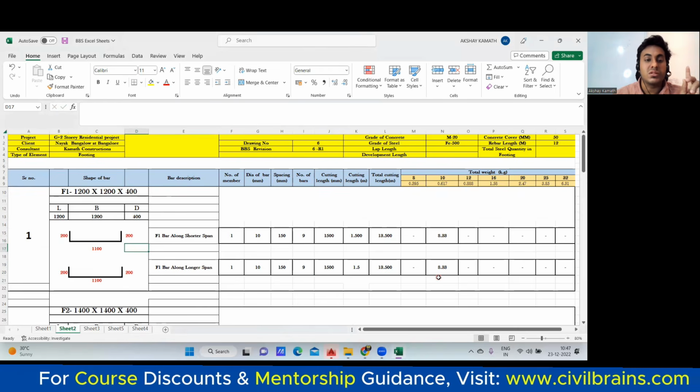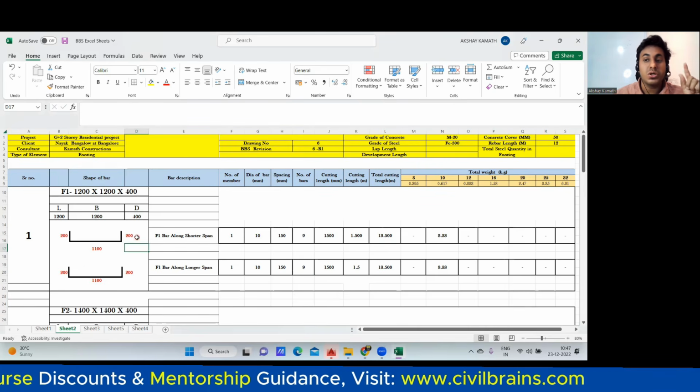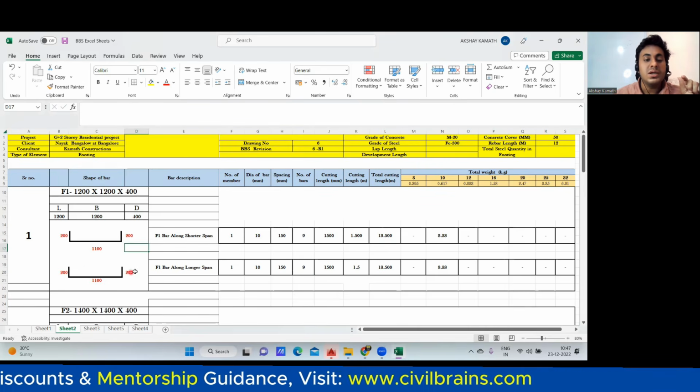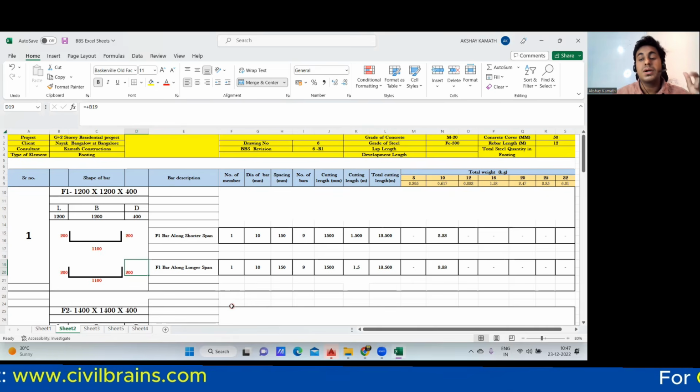So we have taken two cases. One case where the bend deduction has to be applied, and you don't have to take the complete 2/3. Here, no bend deduction, but you have to take 2/3. In this way, there may be another company which says that, like we did previously, you don't have to apply bend deduction, and you don't have to take the complete 2/3 depth. Accordingly, you can work out, based on what the companies follow, right?